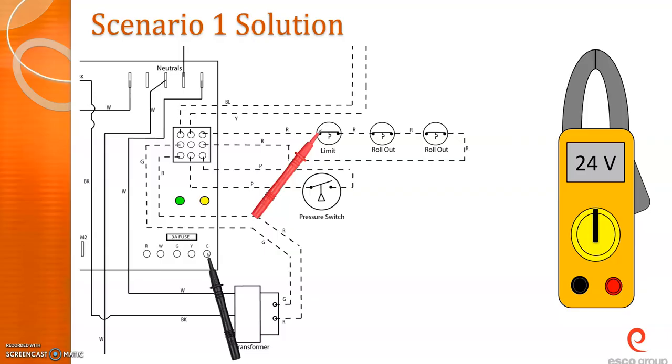That can be a power wire, but it works better, in my opinion, if you put it on common, because common is a neutral. Now, don't get in the habit of troubleshooting to ground, because ground can give you a lot of numbers that aren't really there, that's not accurate, voltages that sort of want to go all over, and so you really want to compare it to a known point. So going to common is a good technique. And so in this case, they've planted their lead on common, and then they're going to just start checking things.